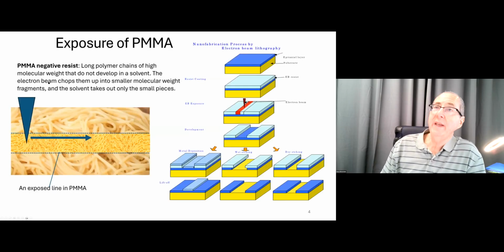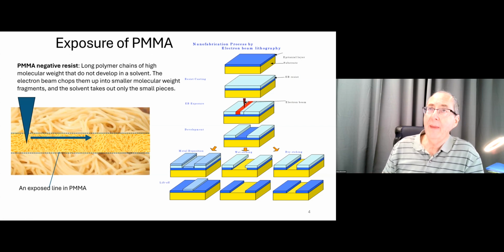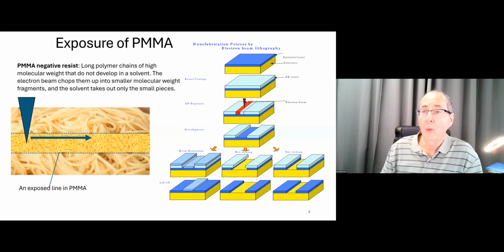Okay, so what is electron beam lithography? In fact, I'm only going to talk about PMMA resist. I'll bring up a couple other resists later, but just in passing. And PMMA, polymethyl methacrylate, is basically plexiglass. It's dissolved in a suitable solvent, and you spin it on and you bake it. And it's really just a plastic layer on your wafer after you spin a thin resist coating.